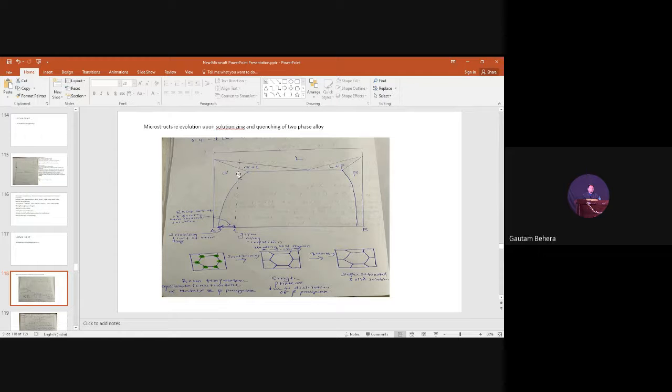Precipitates. Yes, everything. Any second phase, any carbides, nitrides, carbonitrides, or any second phase, they will become soluble. So finally, when they become soluble, it is a kind of solid solution. So this is forming, you can see. This again has only a single phase, only grains and grain boundaries. This precipitate has been dissolved in this alpha phase region, right?